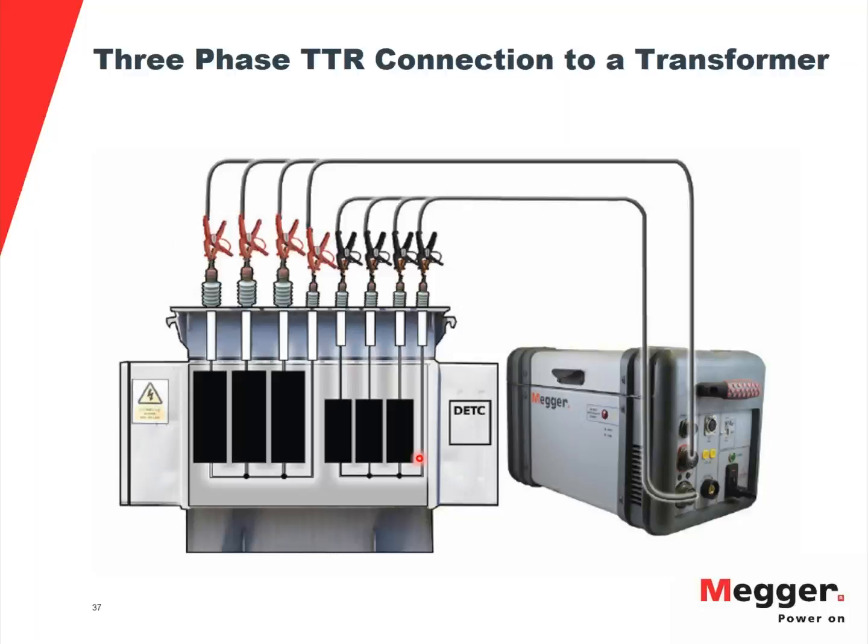Now let's talk about the winding resistance. It goes back to the other question that was asked: I would do H1, X1, and I would also do H1, H2 to take into account all the bushing connections. When I'm testing the secondary side, which is a delta winding, you would notice that it will take a lot of time to stabilize the winding, because it's a delta winding, and that too on the secondary side. Secondary delta windings are the biggest challenge. So make sure that you allot enough time to get a stable reading.